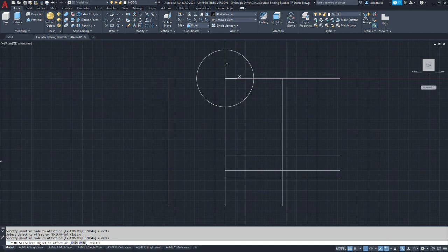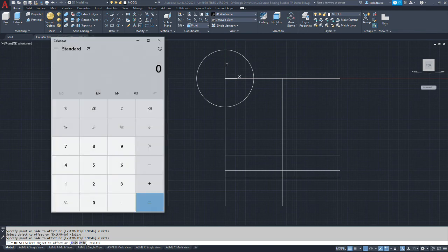It'll help the machinist who's going to machine the part, because when they go to model it, they've got the model actual right on the center of their tolerance, and then it allows them to compensate in their software for cutter deflection and whatnot. So we're going to figure out what the average of that tolerance is, or the mean.